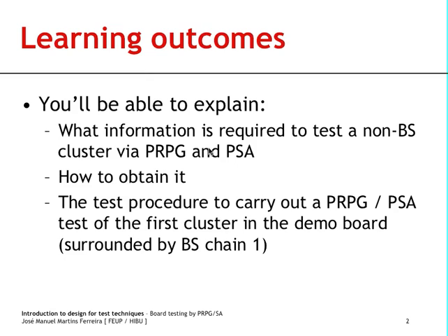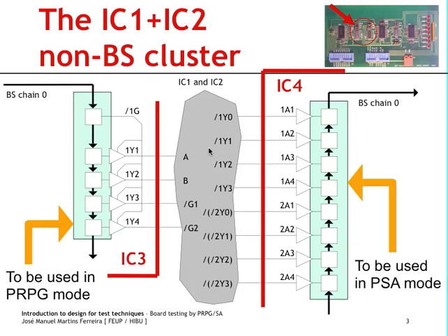And finally, you will be able to set down a test procedure to carry out a PRPG-PSA test for the first cluster in our demonstration board. The first cluster is the one that is surrounded solely by boundary scan cells of test access port number 1.